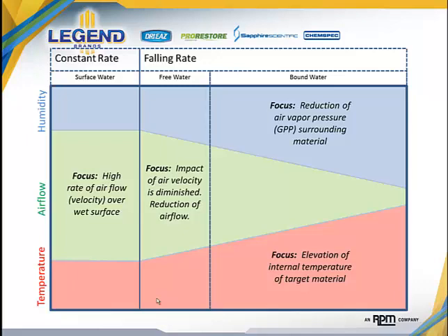What became ever increasingly important was a focus on low humidity or low vapor pressure in the air and ensuring that building materials and the water they were holding were of an appropriate warm temperature. These adjustments help us ensure to maximize our drying rate as we move through the drying process.